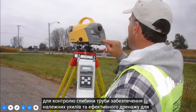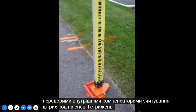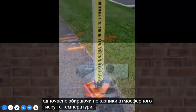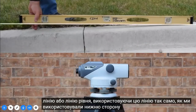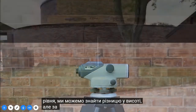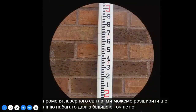For high precision, digital levels with advanced internal compensators read the barcode on a special rod while simultaneously collecting atmospheric pressure and temperature readings. Each of these methods creates a horizontal or level line. Using this line, just like we used the underside of the carpenter level, we can find elevation differences, but with a telescope or with a focused beam of laser light, we can extend that line much farther with greater precision.